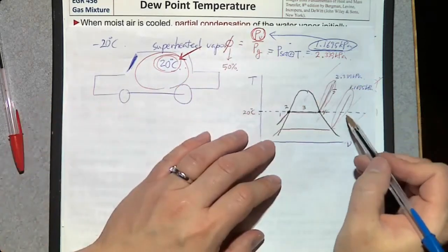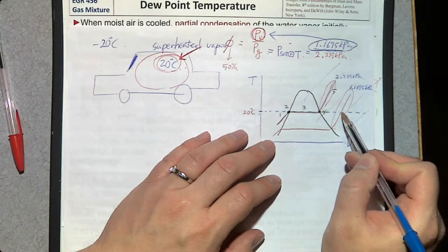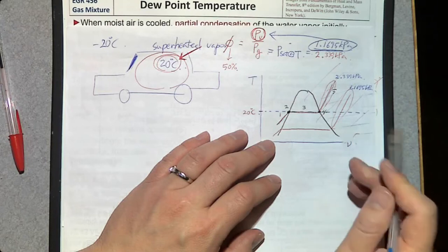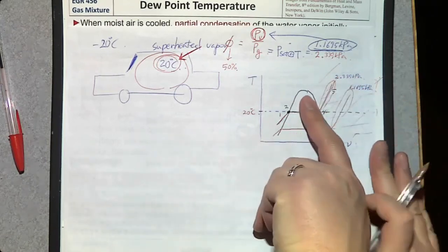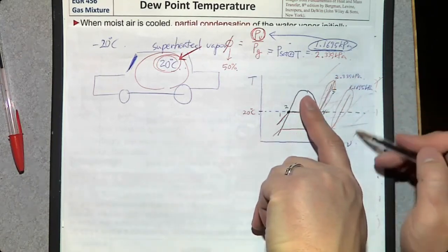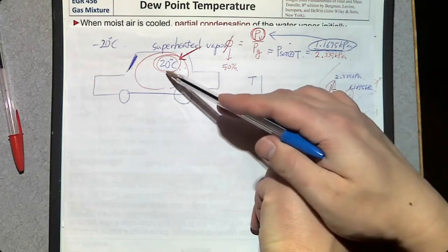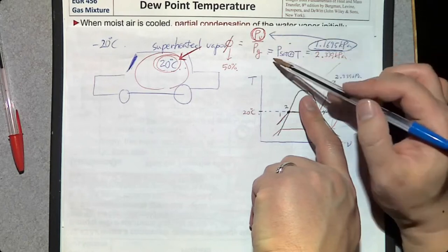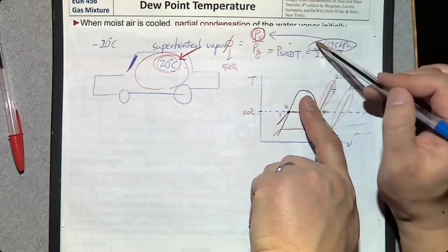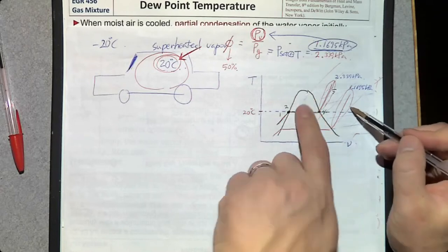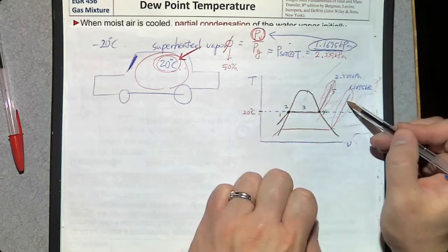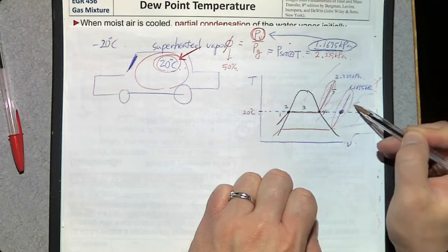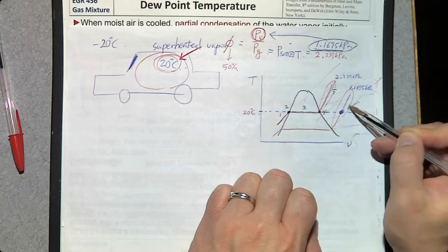So the system is supposed to be on the right-hand side, outside of this saturation line. So this is the only possible state for the water vapor of the air inside this cabin. And the partial pressure is 1.1695, this is our system. Presently, our system is right here at this point.